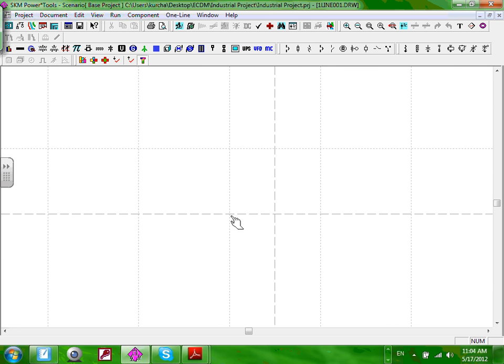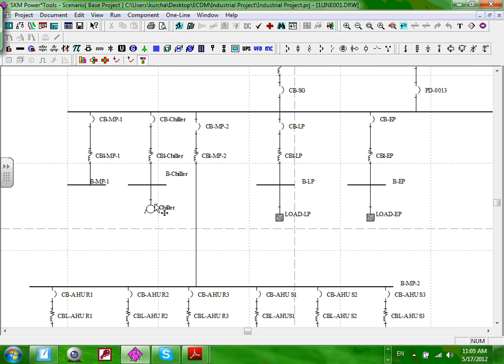Double digits. Okay, we'll figure this out, but I just want to do it for the coordination, guys. To get a better coordination, though, we have to solve all these fatal errors. Fatal errors, guys, are when you don't have an impedance in the cable or you don't have a voltage for a bus. That's really the fatal errors. Okay, so let's do the coordination.